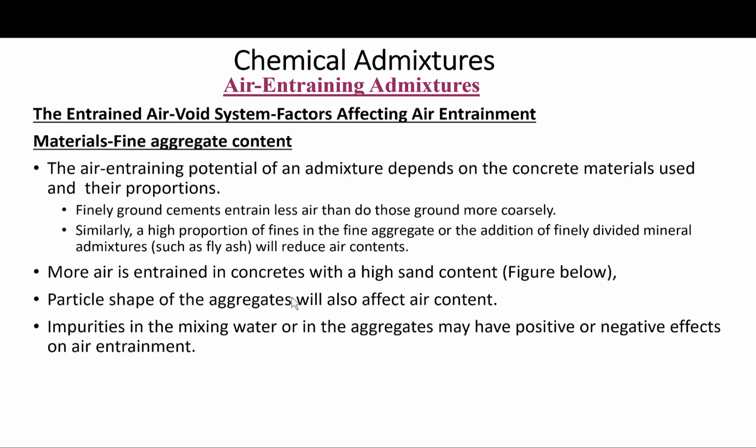Also, remember we talked about the carbon content in some of the SCMs. The carbon present in fly ashes will suppress air entrainment in air-entrained concrete. Cement content also has a marked effect on the total air entrained. At a given dose, lean concretes entrain more air than do rich mixes, and low water cement ratio concretes entrain less air than concretes with high water cement ratios.